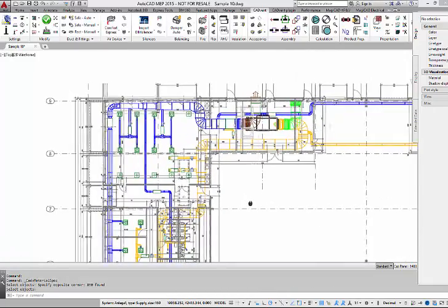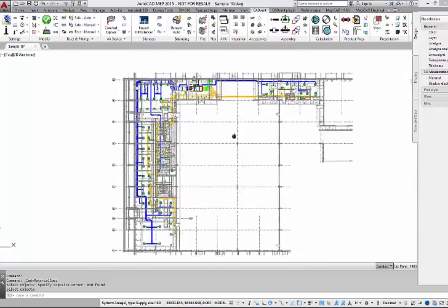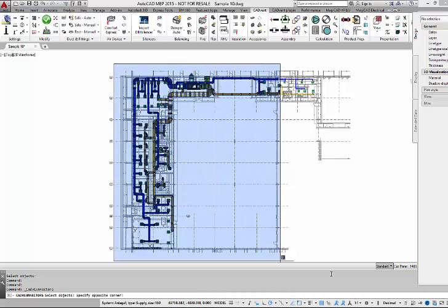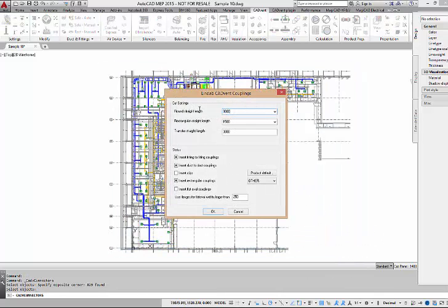And finally, I would like to show you the bill of material functions. As I mentioned before, CADvent is extremely exact in all the details. So before we go for bill of material, we should go for connectors, because everything you designed here needs connectors mostly. So we have, for example, the possibility to say what is our standard straight duct length, a standard rectangular duct length.